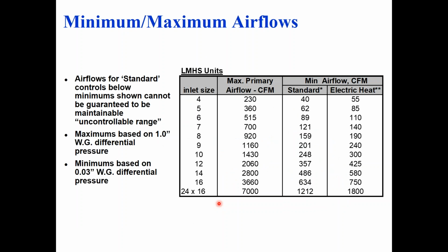There are several reasons for having these airflow monitoring stations on the VAV box inlets. The VAV box is going to be controlled between a minimum and a maximum CFM. That's the main control logic. I did mention a few slides back that there is a minimum operating pressure needed. Usually, as you see on the bottom left of this slide, it's 0.03 inches of pressure that is needed at a minimum to operate this thing.